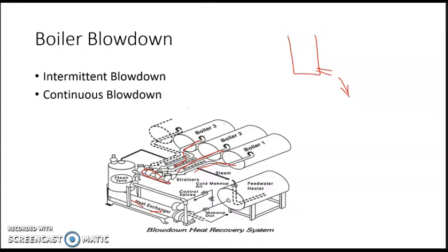continuous blowdown. So with the blowdown, it is possible to have a lower pre-treatment cost, that is, the water treatment cost can be reduced. It will also result in less makeup water consumption, because the quality of steam is getting improved, and therefore it requires less makeup water. And since these solids are getting removed at a constant period of time, the maintenance required in the system is also less. It will also increase the life of the boiler and lower the consumption of treatment chemicals.